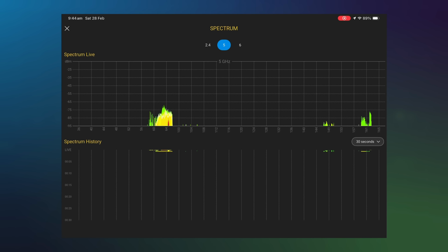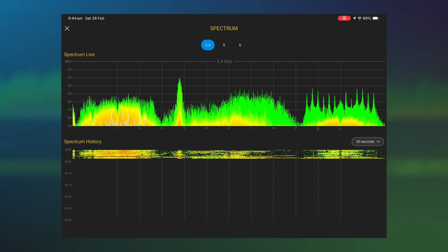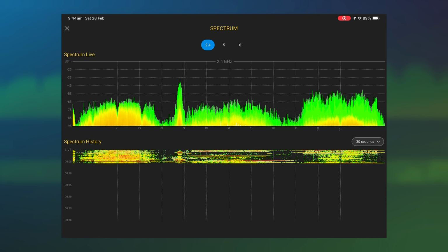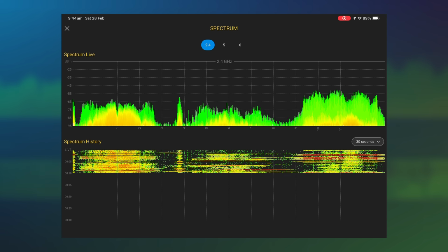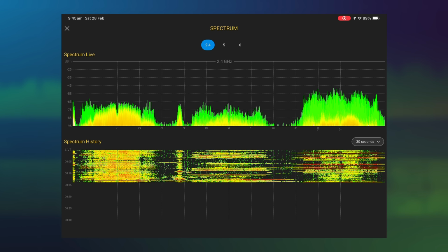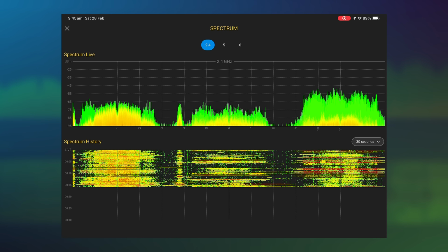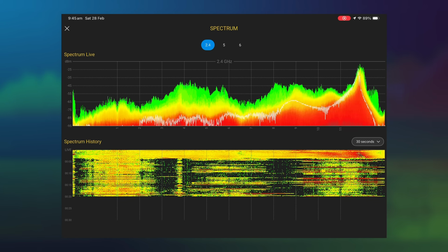If your configuration looks good, it's time to look at the invisible spectrum. RF interference can severely impact performance. The Sidekick 2 features a built-in high-resolution spectrum analyzer that sweeps all three bands, 2.4, 5, and 6 GHz at 50 sweeps per second. This allows you to visualize and catch intermittent interference from non-Wi-Fi sources like microwave ovens, wireless cameras, and motion sensors that other tools miss entirely.